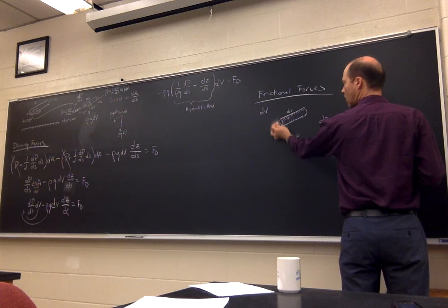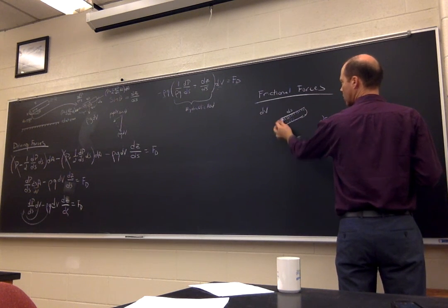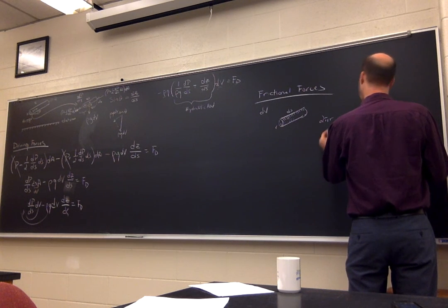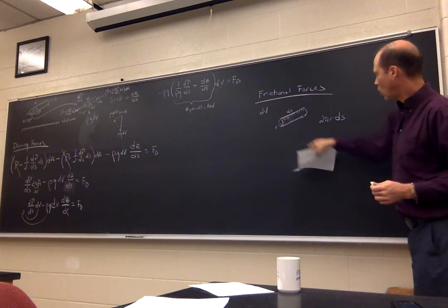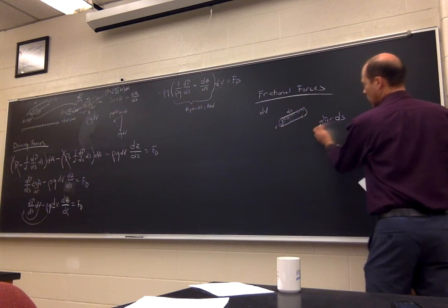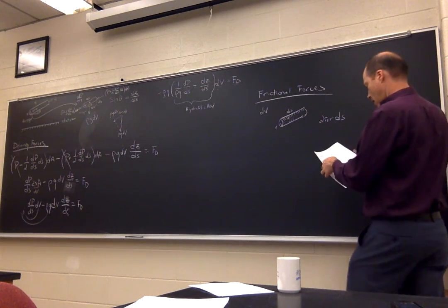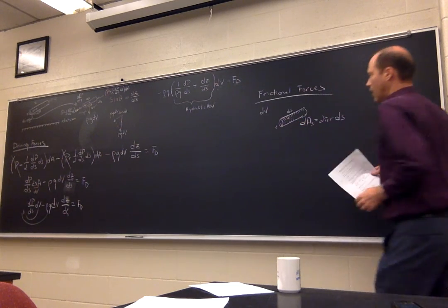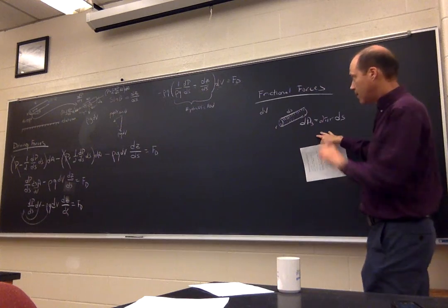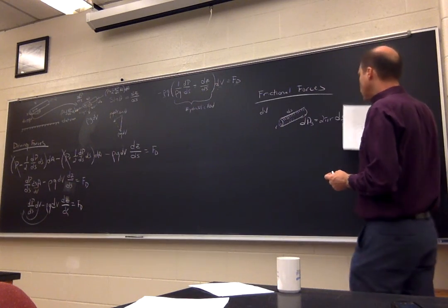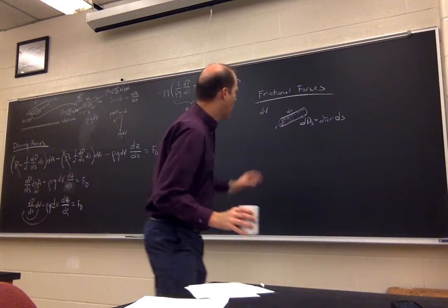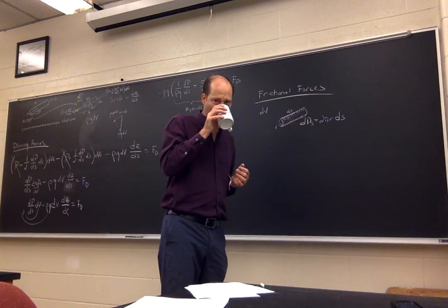So that's the circumference of that circle, times the length of that control volume. So that is our surface area. That surface area is a little part of the total surface area of that entire pipe. Acting on the surface area of this control volume are frictional forces.